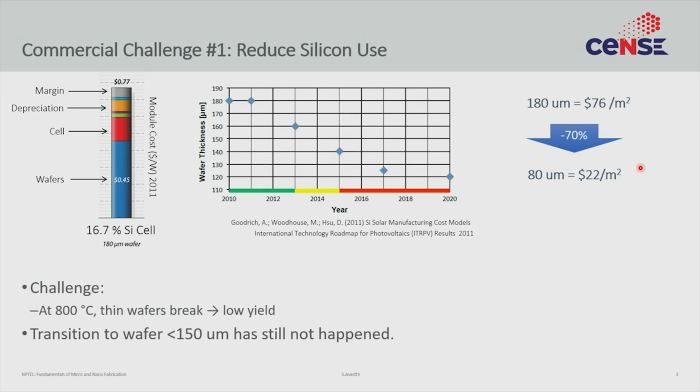So again, if you go back to the earlier lectures on substrate, you may remember the discussion we had on the typical thicknesses of silicon wafers. When Intel does the CMOS processing, a 6-inch wafer is around 700 to 800 microns thick. Intel has that thickness because it does not want any of the wafers to break. So it makes a thick piece of silicon that is robust. It can be taken to high temperatures, it can be taken to low temperatures. You can do rapid thermal processing on it without the stresses becoming so large that the wafer breaks.